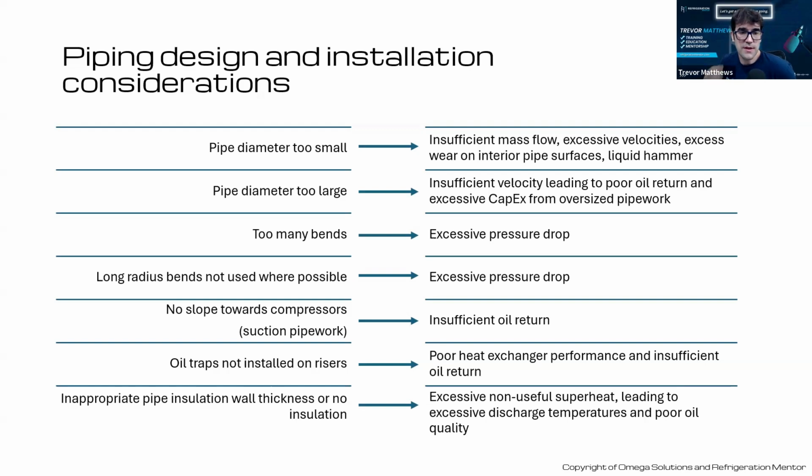Yeah, I have a few questions on that one. One of the things about insulation that I learned from you and Nabil was that you have useful superheat and non-useful superheat, and you can pick up a lot of non-useful superheat through the suction pipe insulation. So a lot of people think, well, I've got insulation on it, it's not gathering any heat. Do you want to talk a little bit about that? Can a suction line pick up heat even though there's 1-inch insulation on it?